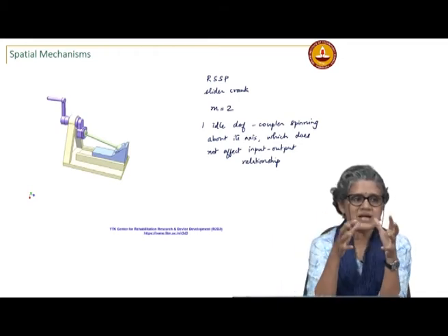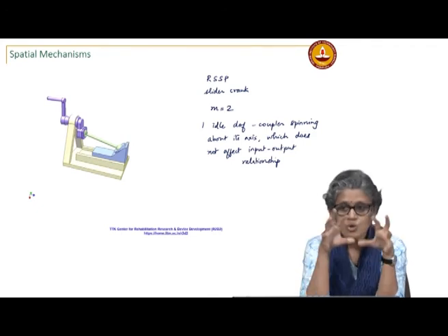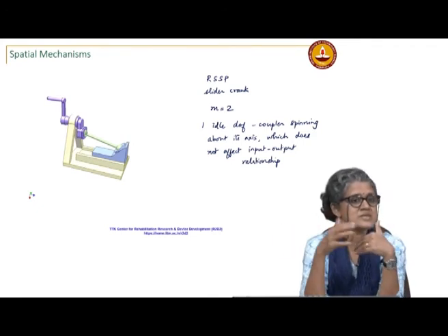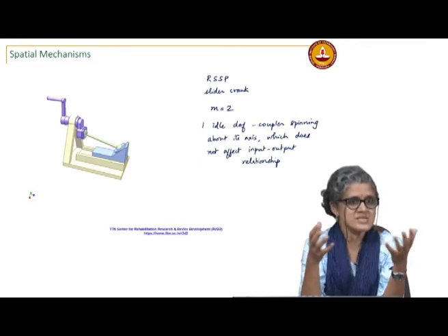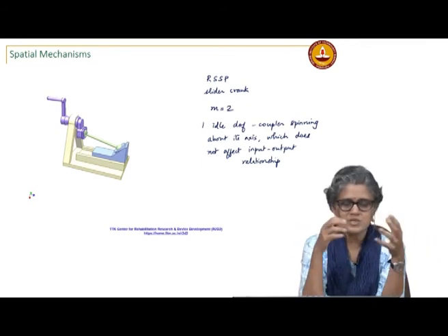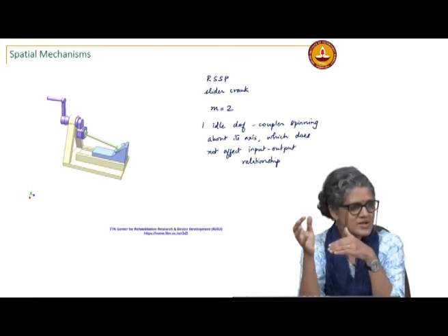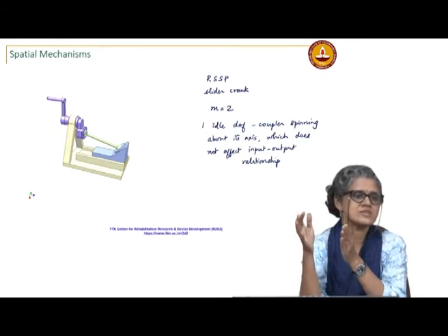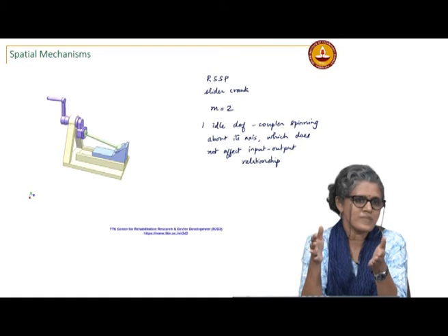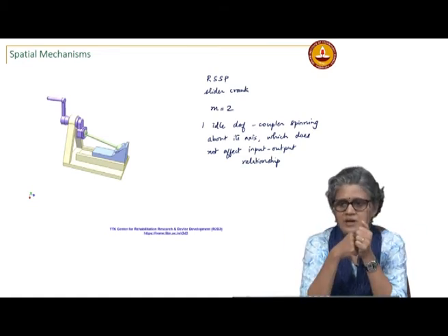That is the idea behind robotics: you attach coordinate frames and then establish the relationship between them, because then it becomes easier to describe the motion of all the points of interest, since the points on a specific link will be completely known with respect to the coordinate frame on that link.